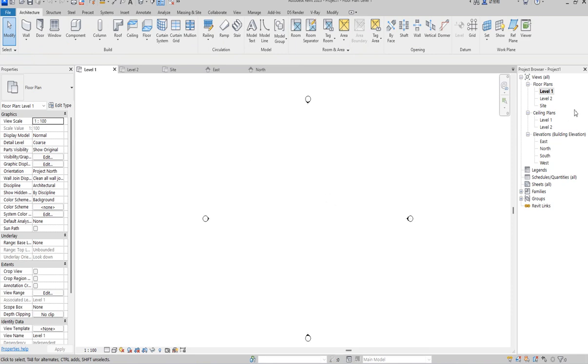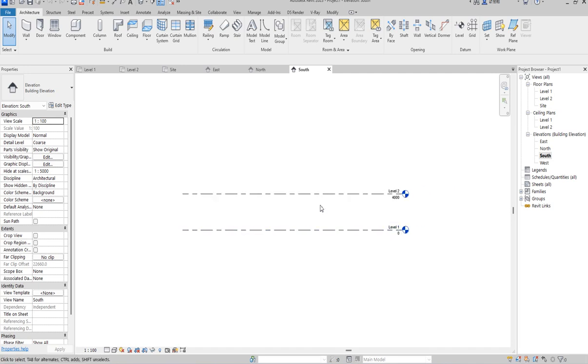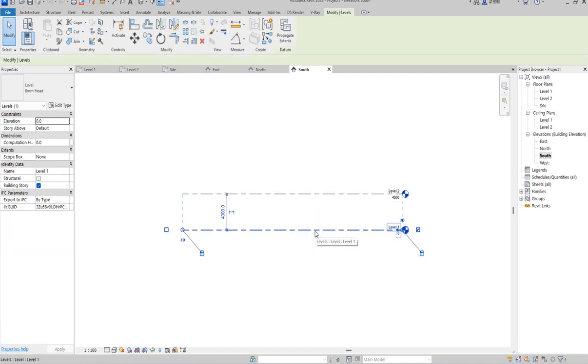Most of this we are going to come back to and cover more. I can't draw without having one thing in place. I call it the foundation level. So how do you create the foundation level? Go to any of the elevations, say the east elevation. What you just need to do is click and create similar.